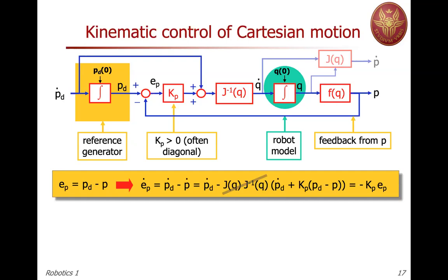Indeed, if you look at the equivalent joint space motion, and you are starting with one component which has 0 error, and the other component which has not, then during the transient in the joint space, everything gets mixed. It's exactly the opposite situation. When you decouple in the joint space, you have coupling in the Cartesian space.